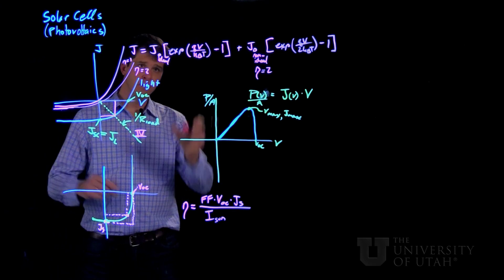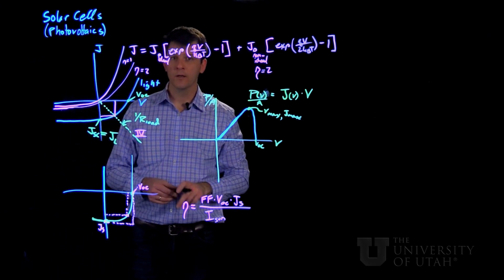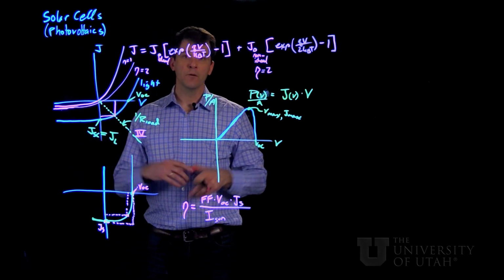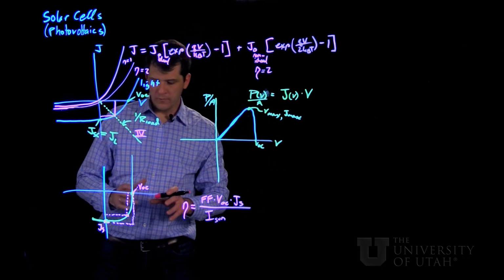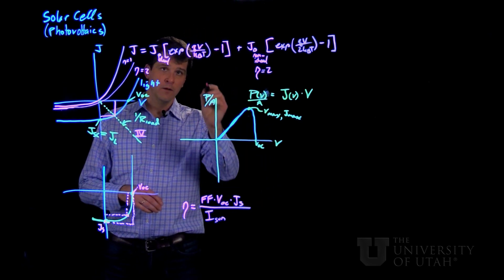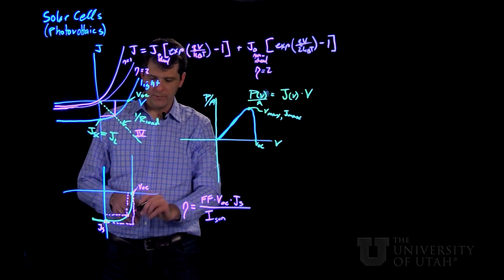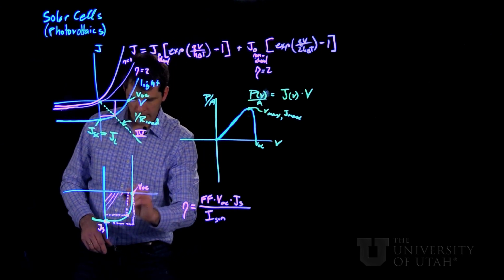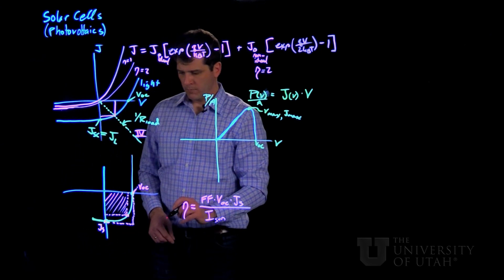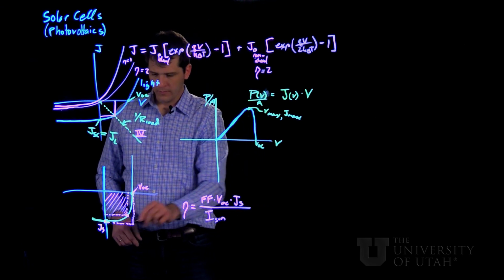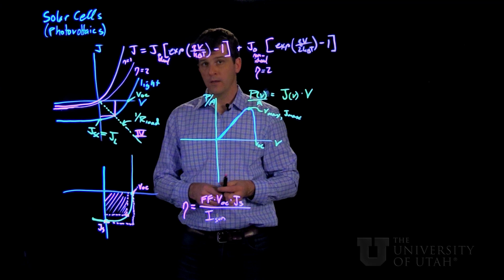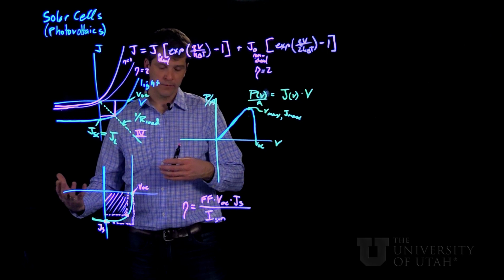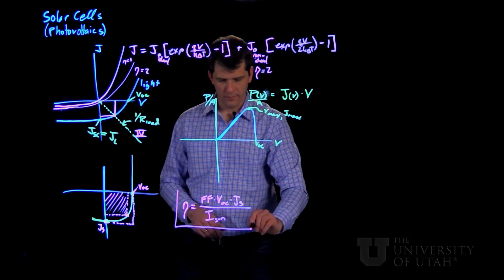And obviously if you have an exponential function like this, it's never truly square, and the highest fill factors are in the high 70 to low 80% range. So for the most ideal diodes ever possible, you can define a limit there that's something around 80%. So this is the actual power that we'll get out compared to the maximum theoretical power rectangle if we had some non-existent device that could actually operate at both VOC and JSC simultaneously. So the power efficiency is defined like so.